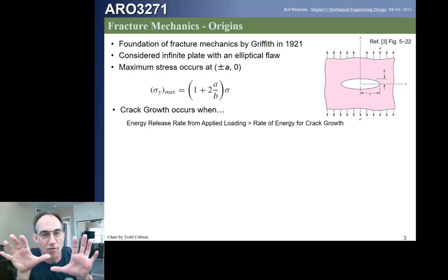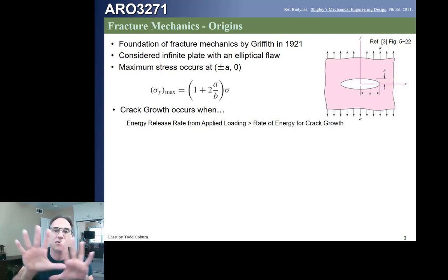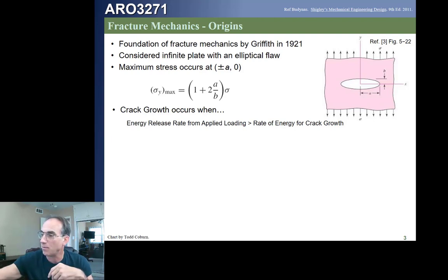When we use this word far field stress, what we really mean is, we've got a semi-continuous structure, and what's the stress level if there was no problem, no cutout? Normally, let's say we have a part loaded with a force P, we've got P over A as our gross stress. We could call it the gross stress, the average stress, and if there's no little cut or hole, that's also the net stress. But if there's a hole, then we have a net stress and the gross stress.